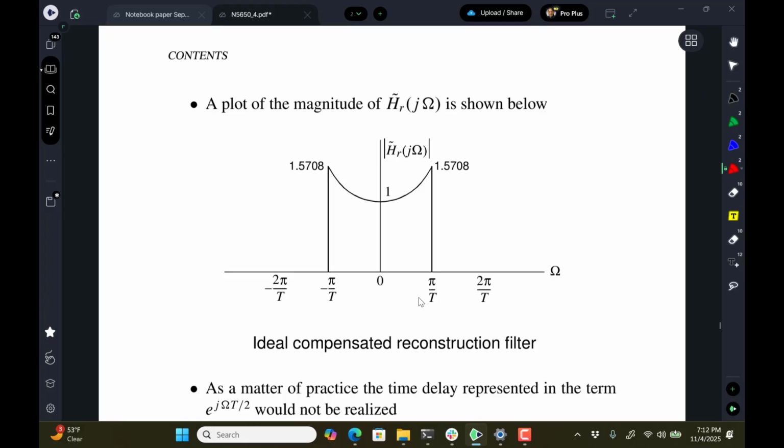There'll be a comment in the hints page when I push that up, perhaps tonight. Because you've got a roll-off in the spectrum, when you design your filter to roll off and you look at it in dB, it's not going to be a straight line. It's going to have a curvature to it, because a 1 over a slope becomes a parabolic shape. It has a curved shape to it.